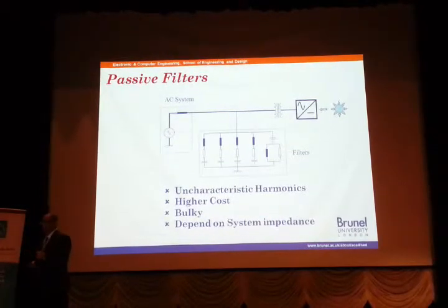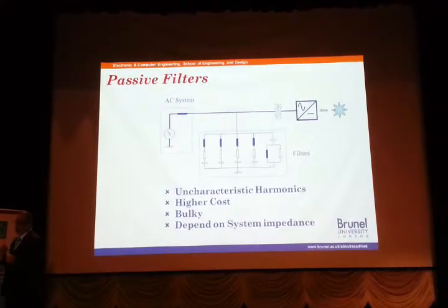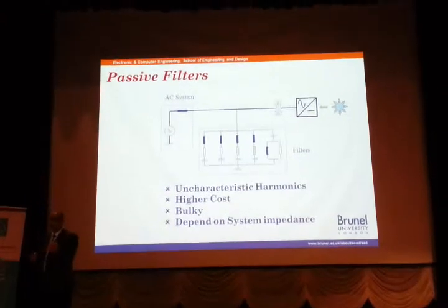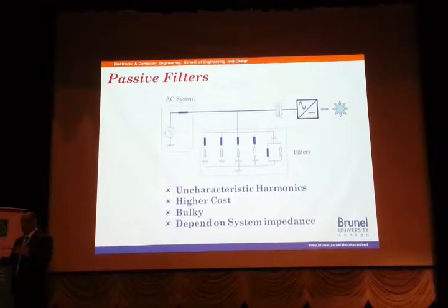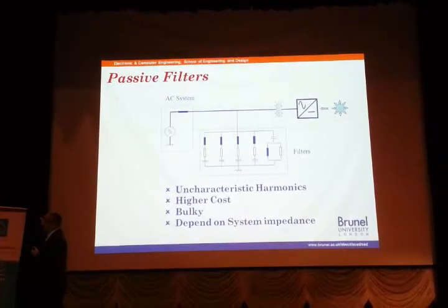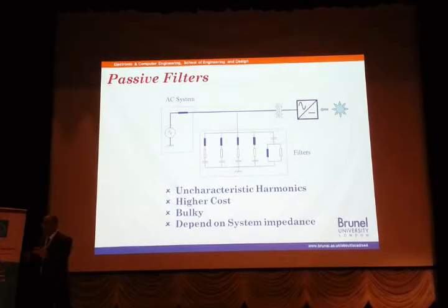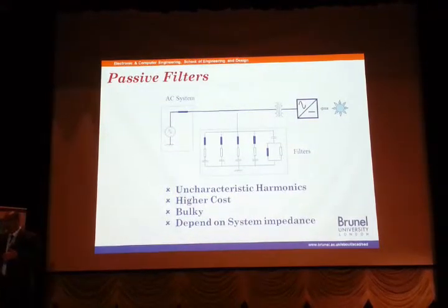Yes. Excellent question. That's what I will talk about next. You are absolutely correct. What we have here is what we call a passive filter, which is tuned for some specific harmonics, and these are some of the disadvantages we are facing. Now, in order to overcome this problem, we have an active filter, and the active filter does exactly what you are saying.